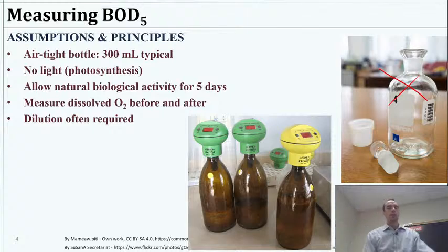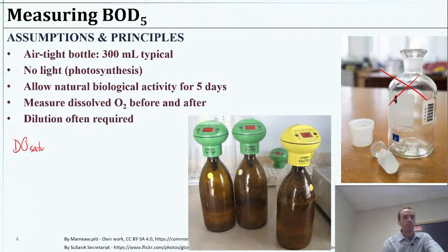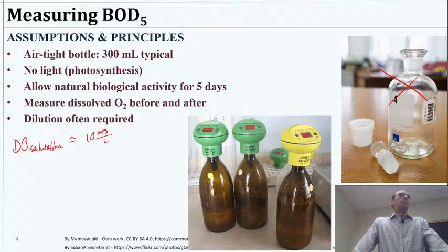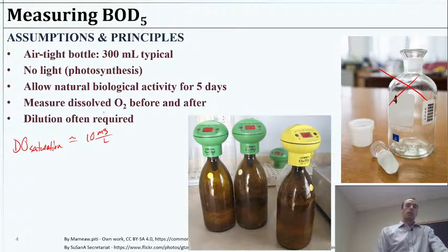Now, we have a kind of an inherent limitation, because DO at saturation is not a very high number. That's usually somewhere between 8 and 10 milligrams per liter at room temperature. If you get colder water, you can get a bit higher. You're never really getting above 20 milligrams per liter. I think 18 might even be the upper limit for like water that's about to freeze.